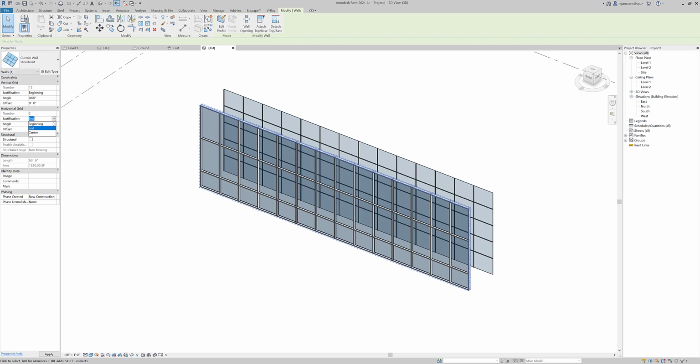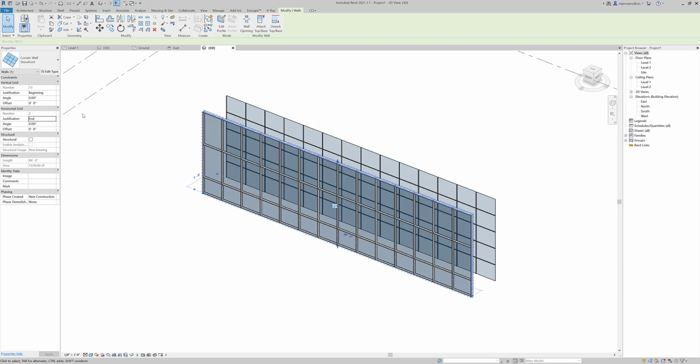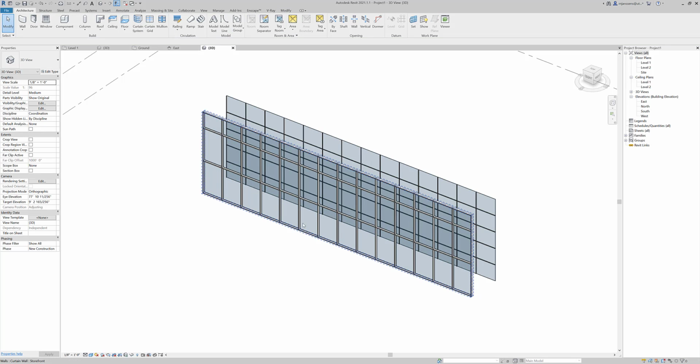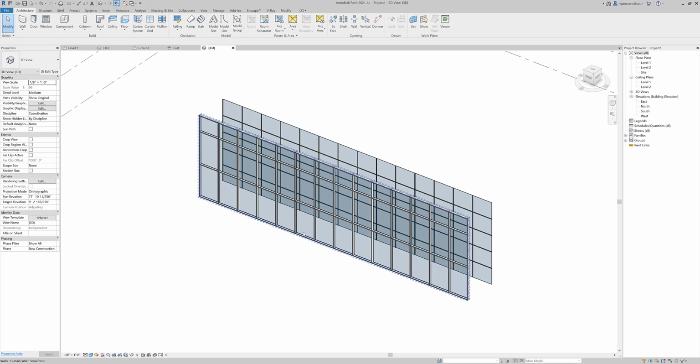You have to be a little bit careful with this because you're going to have doors in here, so that might disrupt the rhythm. We're not really focusing on doors. But just keep in mind, there's a logic to why the storefront begins at the bottom and ends at the top. So you can put an 8-foot door in here, two doors in here based on a 5-foot grid.